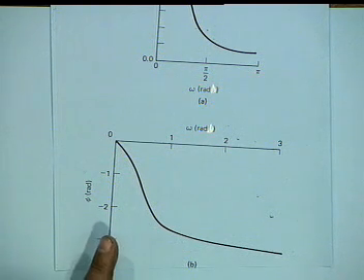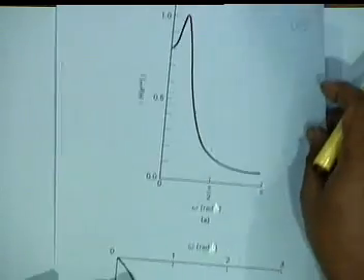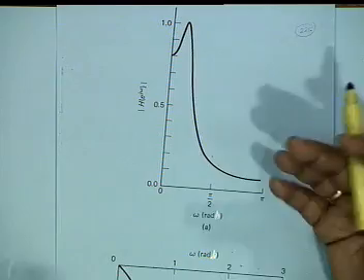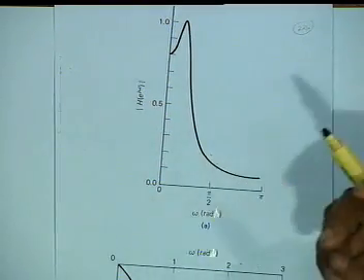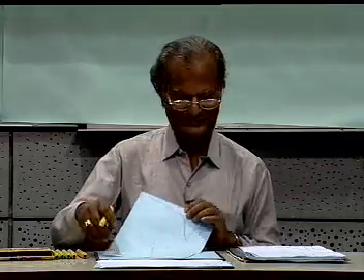If you are doing the magnitude calculation on MATLAB, there is no reason why you cannot use it to find the phase response also. And I must point out, this is the principal value, because phase is ambiguous, isn't it? Twice n pi plus etc. This you must take care.